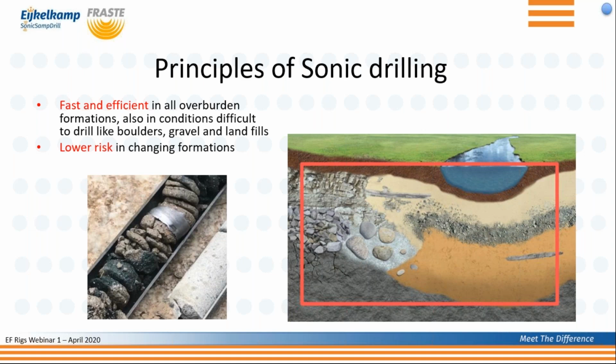If you have compact or hard materials where there is no space between the particles, then rotation can be applied. By doing this, it will give you a really efficient hammer. Overall, there is much less to consider using the 150 Hz Sonic. It provides a significantly lower risk when drilling through mixed formations when compared to conventional methods. What we have here shows the core sample taken from a concrete slab with a 20mm thick steel plate. It was taken at the Royal Eijkelkamp demo day last year, and it took us no more than 5 to 6 minutes.